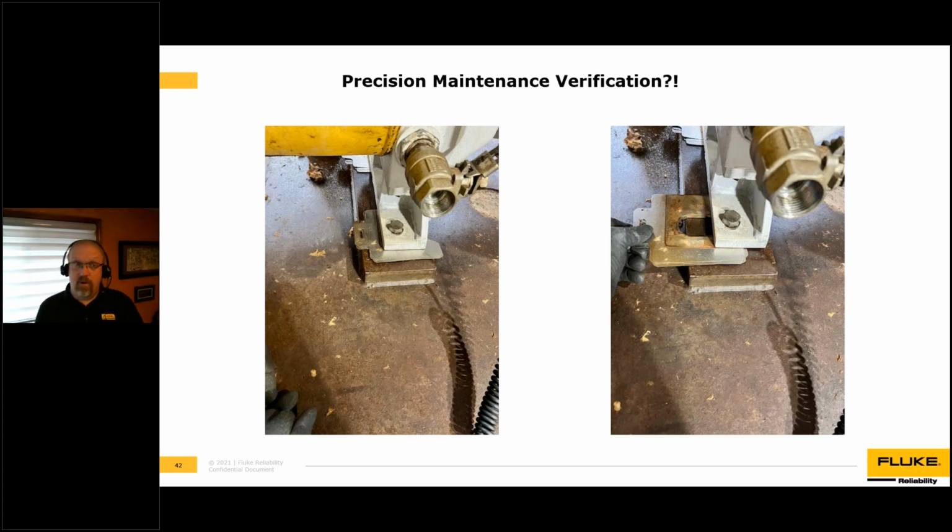Here, we see a brand new black liquor pump. The previous pump had failed, and when the maintainers installed the new one, they signed it off as completed. This included the alignment of motor to pump. The pump that they installed had a difference in overall height from original to replacement, therefore required shimming to alleviate the pipe strain, which is fairly common in older plants.